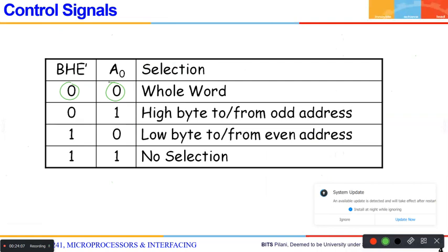See, your microprocessor instruction need not always be 16-bit. In this case, it is MOV 4374, BX. It need not be that. It can be MOV 4374, BL. When the instruction is 16-bit, it has to read 16-bit data.